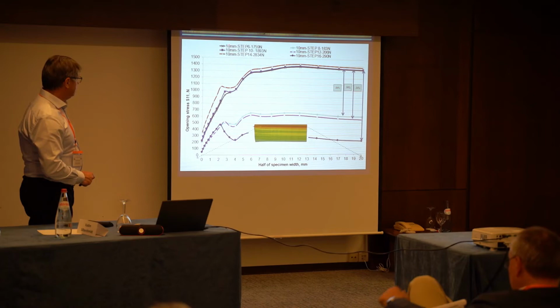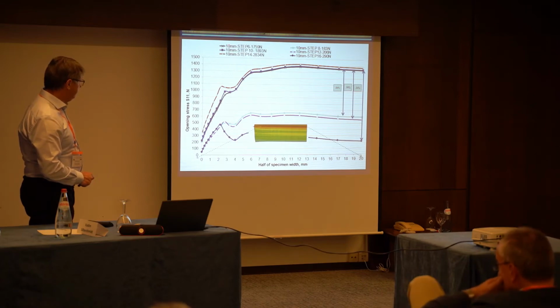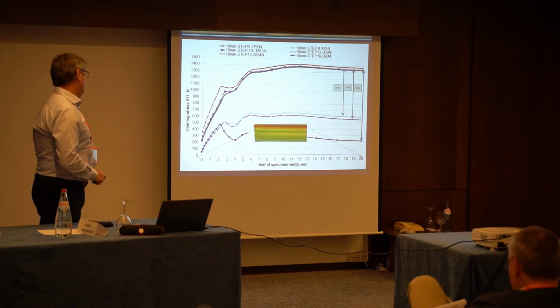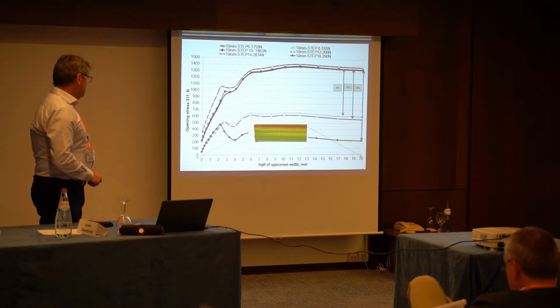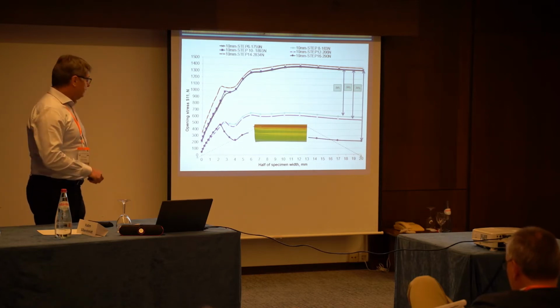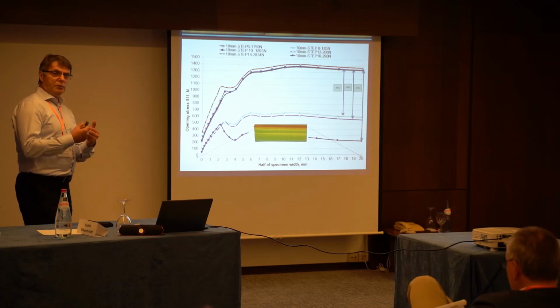So now we want to consider in our analysis the loading point for the specimen which was bent 10 millimeters. And here we now follow the opening stress. While we do not start from zero, this is the influence of residual stresses. But these residual stresses we also got from numerical simulation.